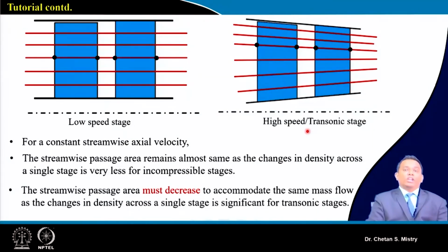Now before going into the detail, we must understand we are discussing the design of a transonic axial flow compressor. We have discussed the subsonic compressor design, in which the pressure ratio, the pressure rise expected, is lower. That means my inlet area and outlet area can safely be the same. That's the reason why we have this kind of configuration, where we do all our calculation at the mid station, and after that we do our calculation at different stations.